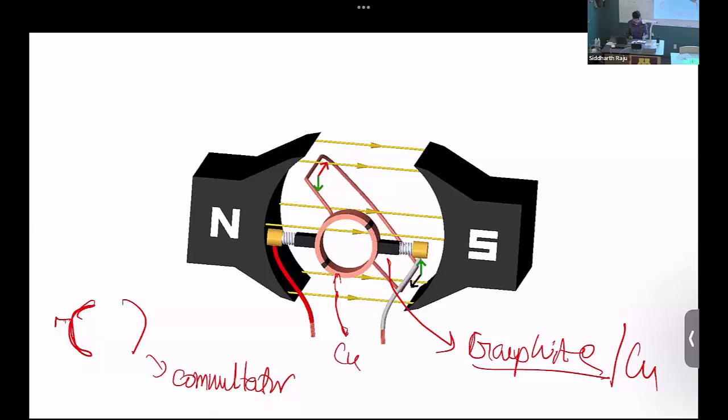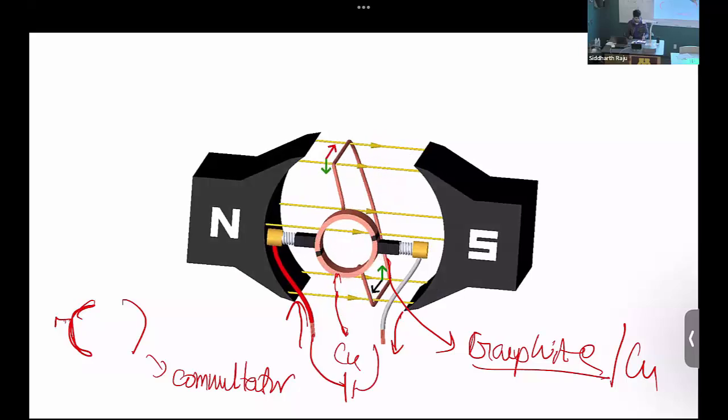So we are going to pass positive current through this positive conductor that I marked here in red, and the negative conductor is the return, and then we connect a power supply outside. If you look at this, now we have mechanical isolation. The current can go through this conductor without the external world getting twisted around. And if you look at what happens to the current on the conductor on the left, keep an eye on when it goes to the other direction. Fixate your eye on this copper ring. Once this black part comes here and this copper ring makes contact with the negative, you'll see the current reverses to the other direction.